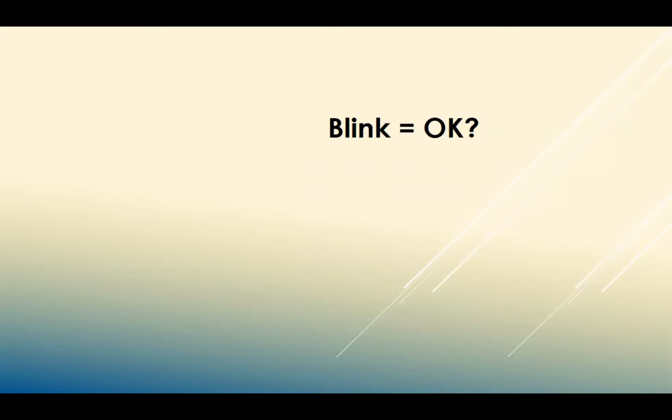Some people have bought Nanos and they don't blink. Most providers, when they sell you a Nano, put on a program called Blink. You put the power on and you'll see the LED flashing. And that tells you it's got a program on it that will flash an LED. If it doesn't have a light on it, people assume it's broken. It's not. It may simply not have been programmed with the Blink. Or it might not even have a bootloader on it.